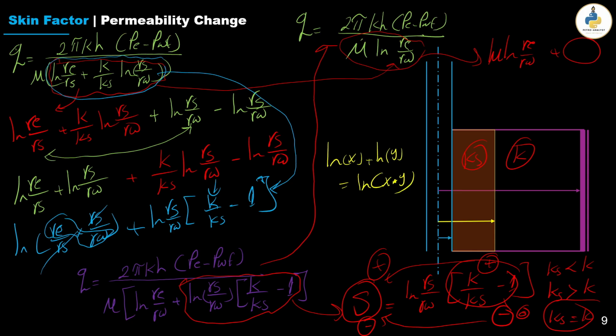And now we have gone from the ideal Darcy law into introducing the altered zone and the mathematical derivation of the skin factor, which is the abstraction of the additional pressure drop due to the change or the alteration. It can be physical or non-physical, but let's simplify it as the alteration in the near wellbore zone.